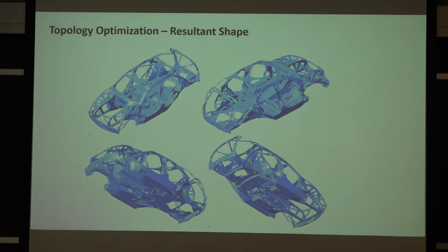So again, we had this packaging space, this packaging volume where we could put load. Only where you can put load. You can't put load through somebody's head. You can't put load through somebody's legs. You can't put load through the engine typically. Okay, so we took this volume that we had. We broke it down into 2.3 million elements. Each of these elements was assigned a density.